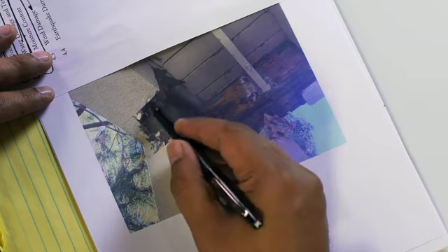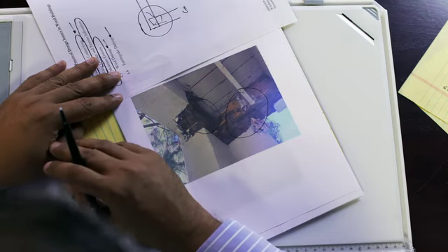And it gets worse as you go to the connections. The interesting thing about these pictures is that if you look at the stucco, everything looks nice and clean. Everything looks pristine. But the minute you take the stucco off, you see that the entire structure is about ready to fall down. So what did I have to do in this case? I had to flag off the building. I had to tell them not to go on the balconies until we could replace this. And again, if we hadn't opened it up to look at it, we wouldn't have a clue.